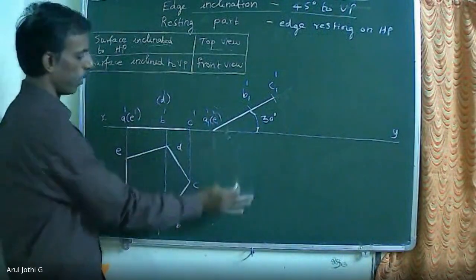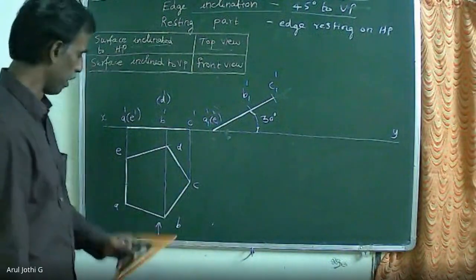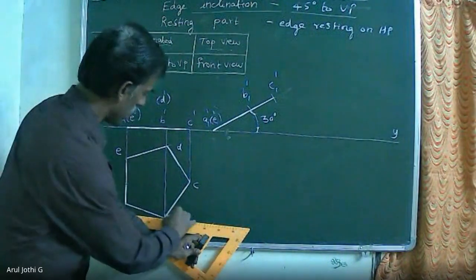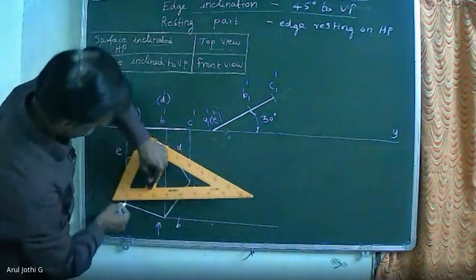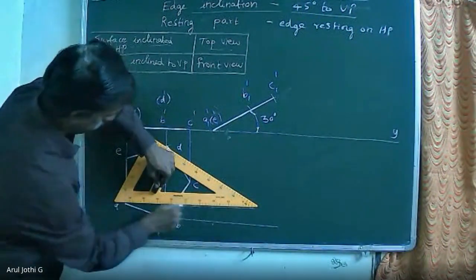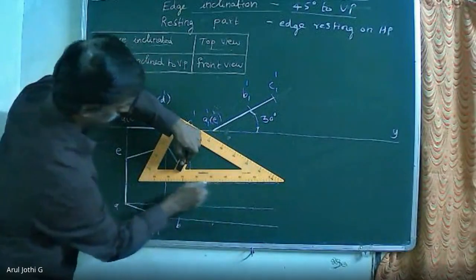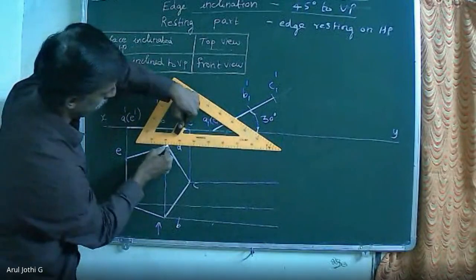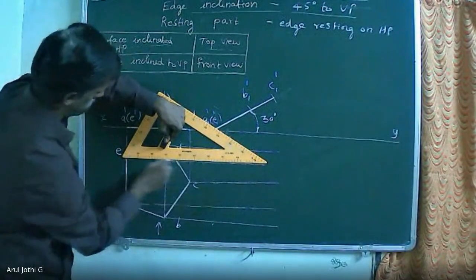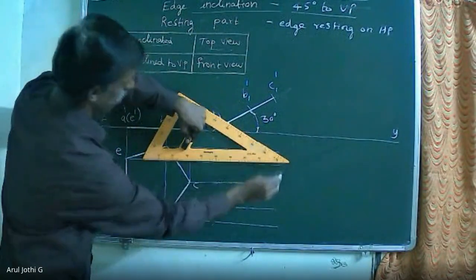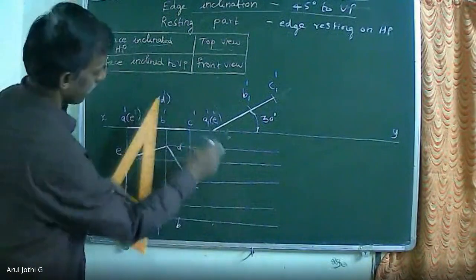Now using this top view and front view, I am going to draw the apparent top view, the second stage top view. That you can construct only by projection lines. Now through all the endpoints, all the corner points of the top view, draw the construction lines. Now extend the corner A from the top view and A1 dash from the front view.